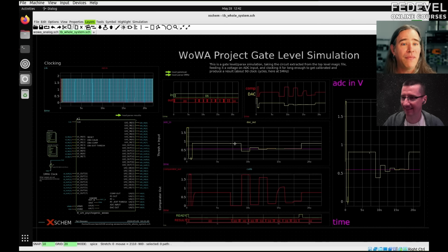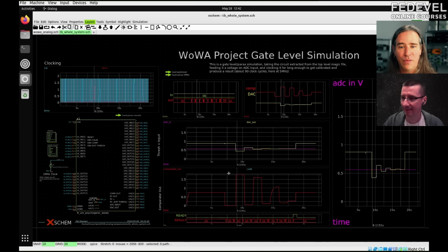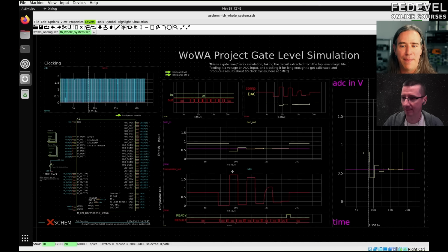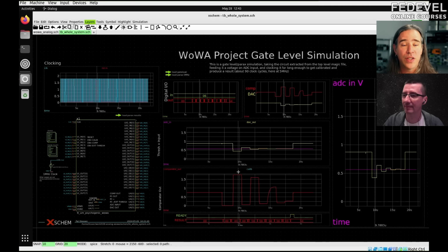So here's the voltage on the DAC. I set it to half. And then I look at the comparator. So let's use a line here to see what we're doing. The comparator says the target voltage here, this purple, is lower than me at this point. Okay, so I'll clear that bit. Then over here, the target voltage is higher than me. So I'll keep this bit.